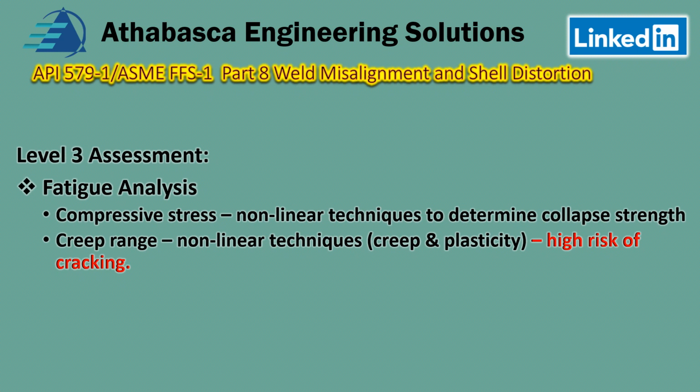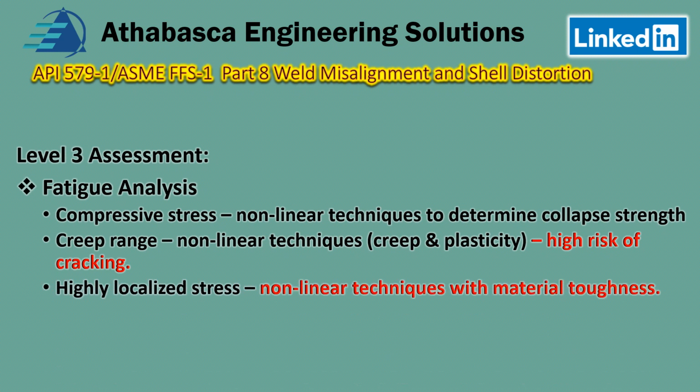Also be cautious, because there's a very high risk of cracking if you have materials running at the extreme of this range. And for highly localized stresses, nonlinear techniques and material toughness requirements need to be thoroughly understood in order to provide this kind of assessment.